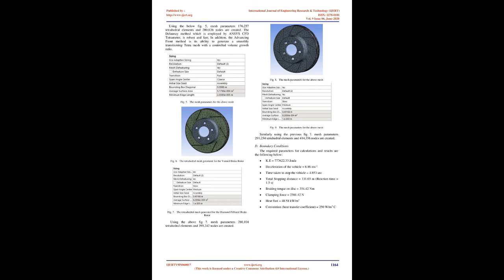C. Meshing. Generating a mesh is an important step in the static structural and thermal analysis, as the size of the finite element is determined by the mesh properties. Finer the mesh, more the accuracy of the results and more the computational power required. The ANSYS CFD tetra mesher uses unstructured meshing technology, which follows an object-oriented approach. It produces the mesh directly from the CAD surfaces, and uses the octree method to fill the volume with tetrahedral components. A robust smoothing algorithm ensures uniform consistency of the components.